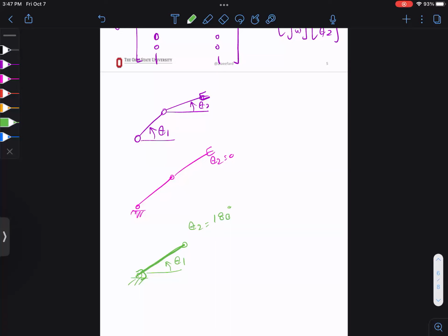Any questions on all of this in general? Yes. So in the singularity, are we saying the singularity only occurs at a set angle for one joint, or could you have it across five joints? You could have singularity in different joints. It could be because of a specific value that singularity happens, or the axes are aligned in such a way that they become redundant and nothing will move.